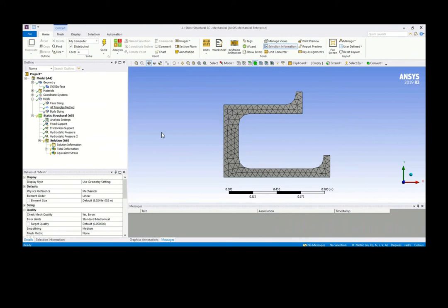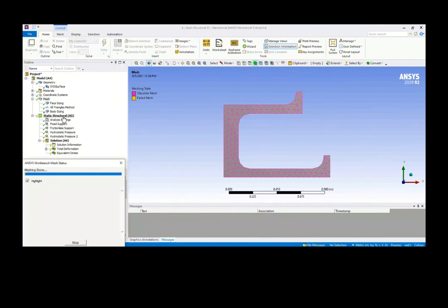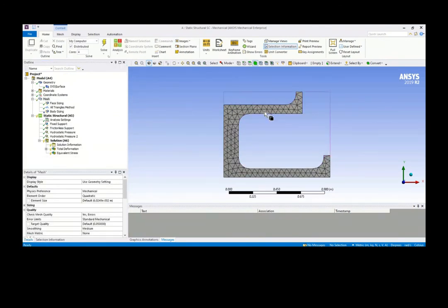All you see is triangle types, and here is linear. Even if you put quadratic, you won't see a node there. If I put quadratic here and generate mesh, it's also the same, but it's the second order quadratic function, and the node in between is there, we just won't see it. So we put linear.